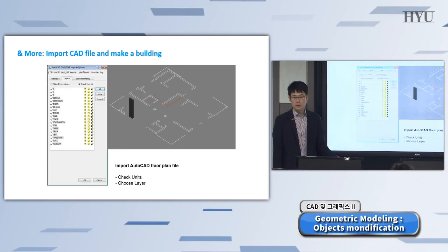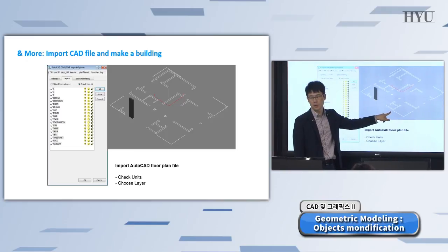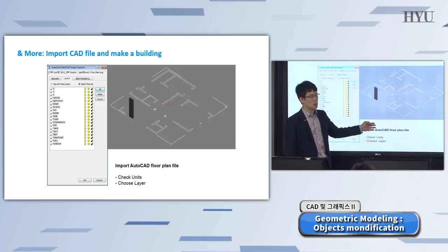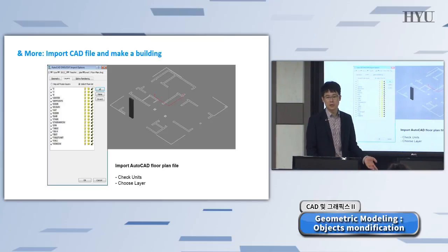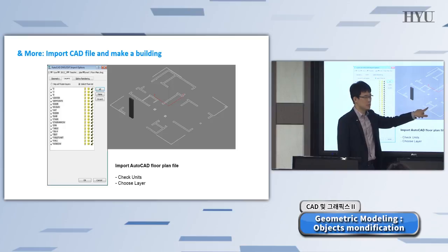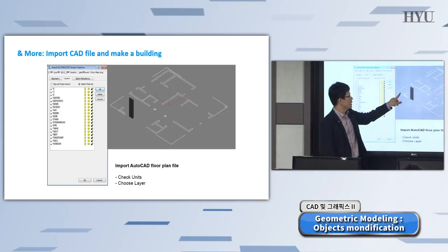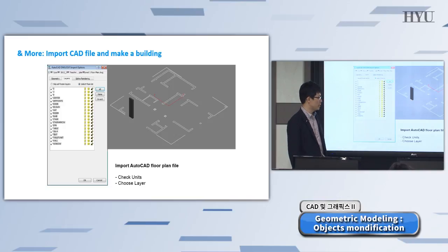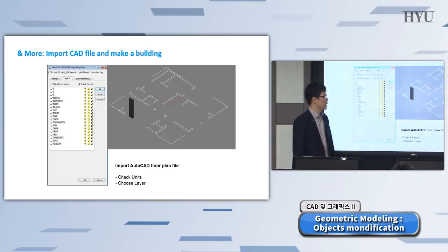But actually, in reality, for architectural design and architectural modeling, those are layers imported from a 2D CAD file, okay? That is why 2D CAD is still important for precision, for layouting, and for some specific early phases of design. When you draw this kind of CAD file or CAD plan, you can directly import it into a 3D application and simply extrude it. And then you can create some 3D buildings and environment, okay? You have to take into account dimensions, units, and so on.